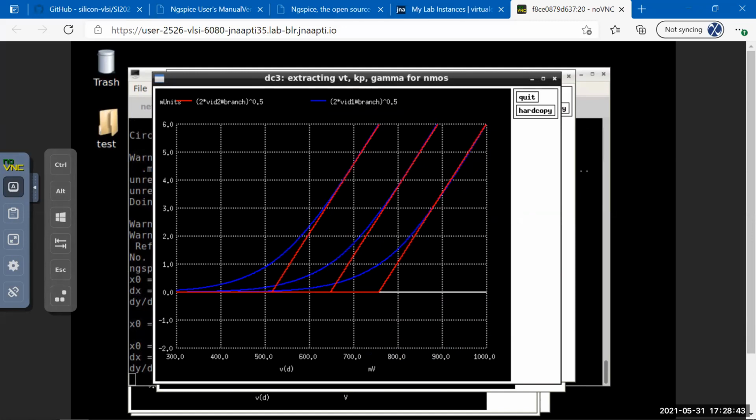But in the real model, you can see that the current really is not 0 when it is less than VT. So this is your VT. The current is really not 0. In fact, you can see it's pretty high. It's 1 milliamp for this transistor here. And this is the area which is called the subthreshold region. Okay, and your gate to current gain is actually very, very high here. The absolute current is lower, but the gain is really, really higher.